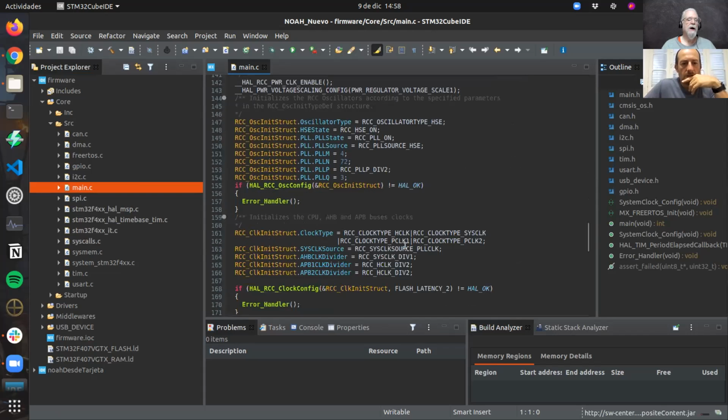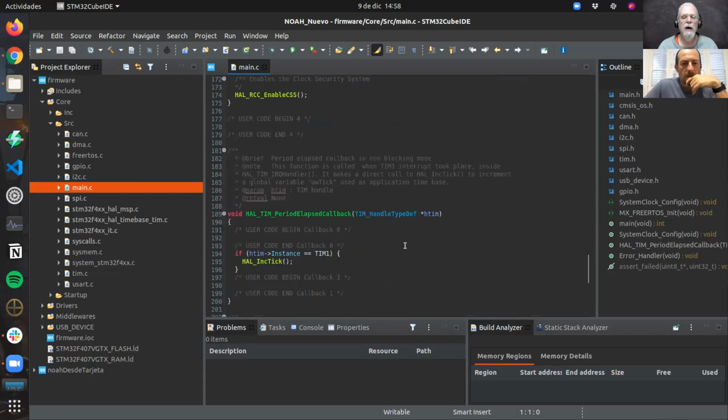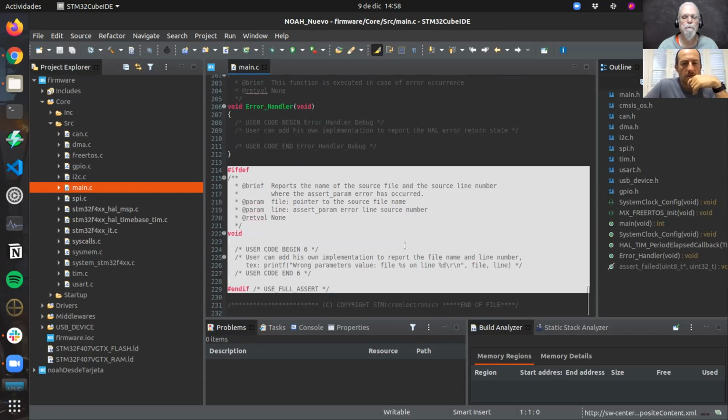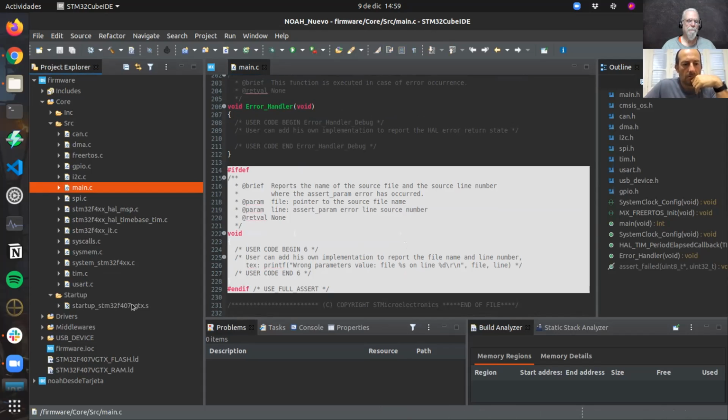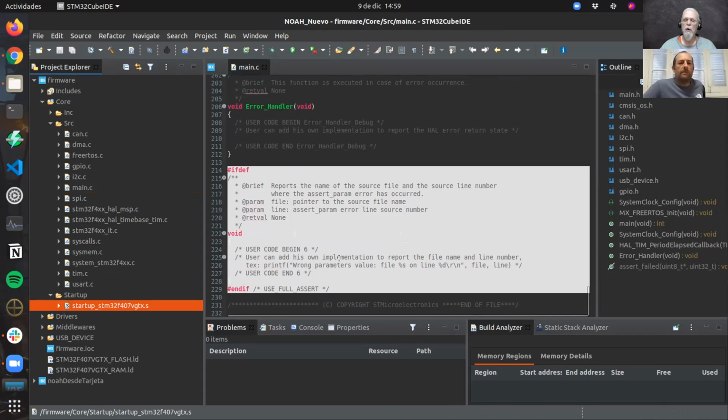Now, when you first started out, I don't see anything naming this, but as you went through the steps to open this, it said, what project do you want to open? Whatever the name for that project was, you want to find that as the new stuff. So don't try to open something called .ioc, because that's not a project. That's simply the pin file.